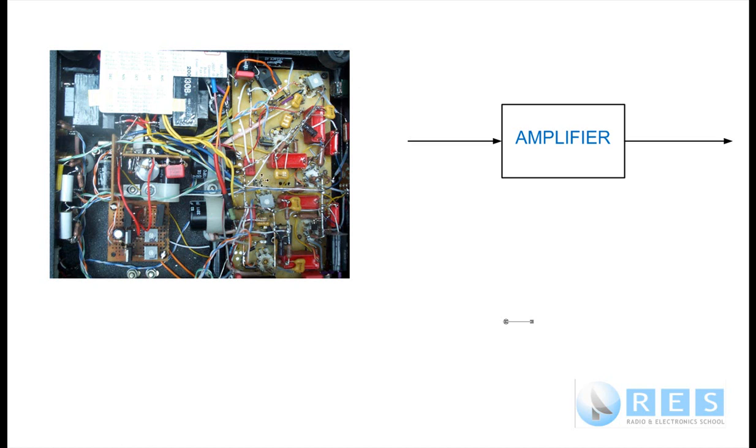If this is an amplifier designed to operate on 7 megahertz, and you might want to transmit on the 40 meter band, and your fellow radio amateurs say to you, hey look Joe, you're transmitting a signal on 7.1 megahertz as well as 7 megahertz. Well, that's probably due to the way this transceiver has been built with all this messy wiring and inductance. The way that would be fixed would be to clean up the wiring or just move it around.